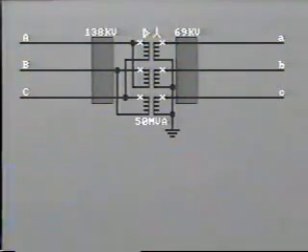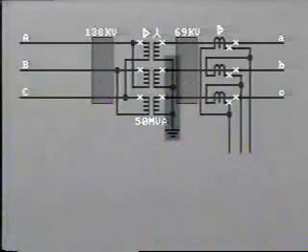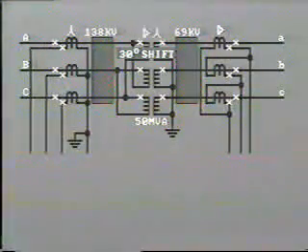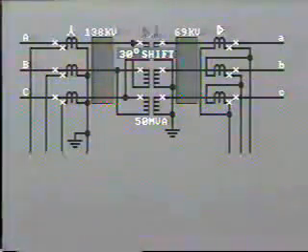Now let's look at phasing for the delta primary Y secondary transformer. The high voltage side operates at 138 kV line to line, while the secondary side is at 69 kV line to line. The neutral of the Y-connected secondary is grounded. Therefore, the CTs on this side of the transformer should be connected in delta, as we have just explained. Having established this, it is obvious that the CTs on the delta-connected primary must be connected in Y so as to correct for the 30-degree difference across the transformer.